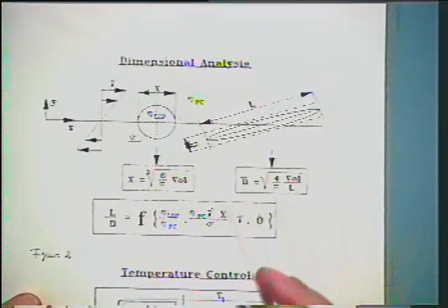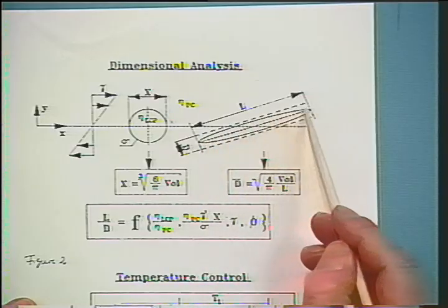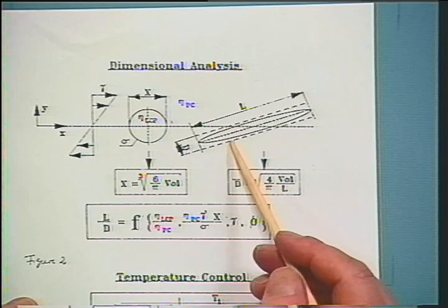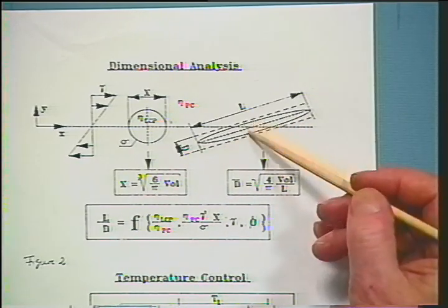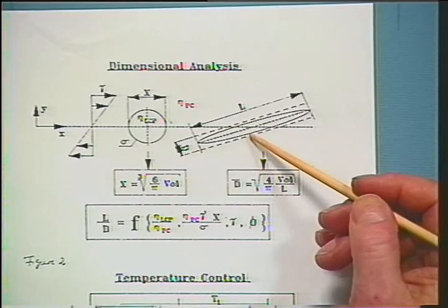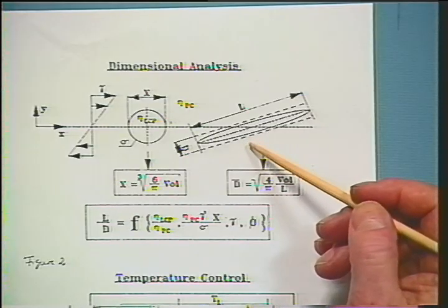Here we maybe start with a spherical particle, and that particle is then elongated into some ellipsoid. Note that it will just be getting longer due to that shearing deformation, but the width is about the same. So it's not an axisymmetric fiber which we are producing. It's more like a linguine, like a flat noodle, which is produced in that type of deformation.